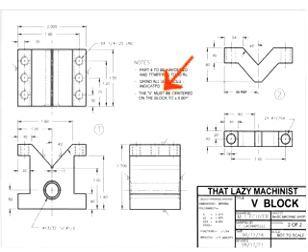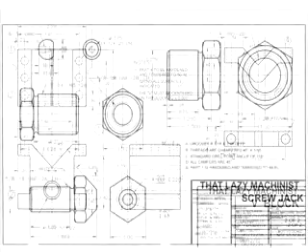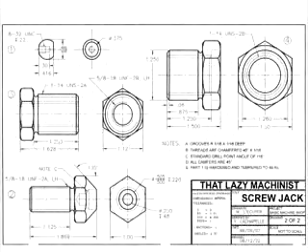The note says that the V must be centered on the block to plus or minus 1/1000th of an inch, and that seems to be some type of tolerancing. In reality, it's a very gauche way of trying to tolerance symmetry, and that really should be left up to geometric tolerancing. But since we haven't seen specific tolerances yet, we'll get back to the geometrics later.